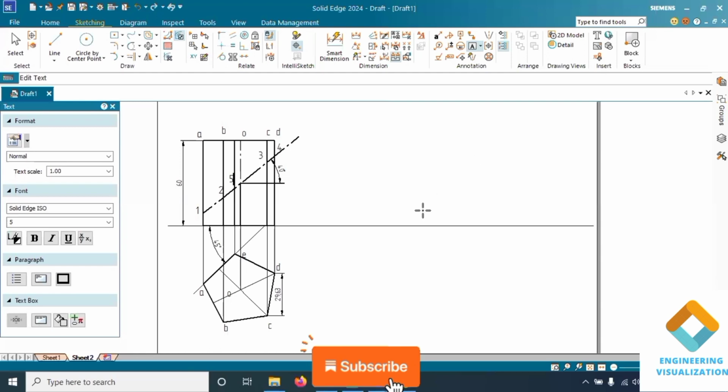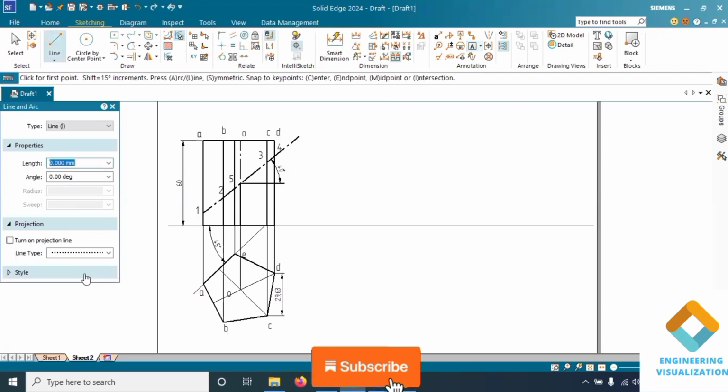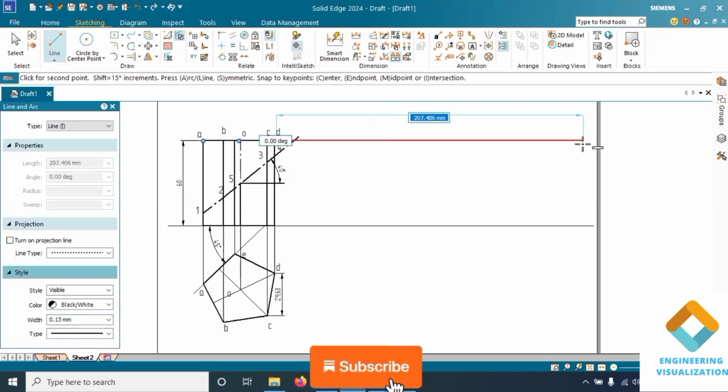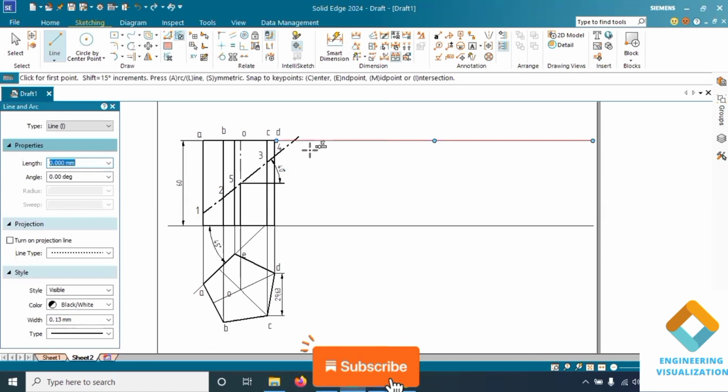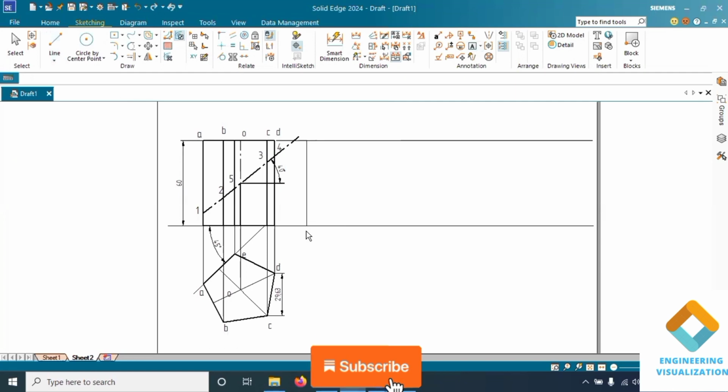Okay, we got the cut points. Now we need to draw the development of this. We know that a prism will be drawn using the parallel line method, so we'll be drawing the parallel lines here. One vertical line you can draw, and then there are 5 faces in the pentagon, so we can draw at a distance of 30 mm.